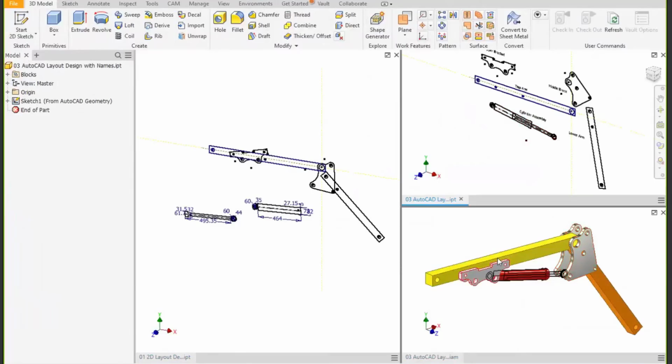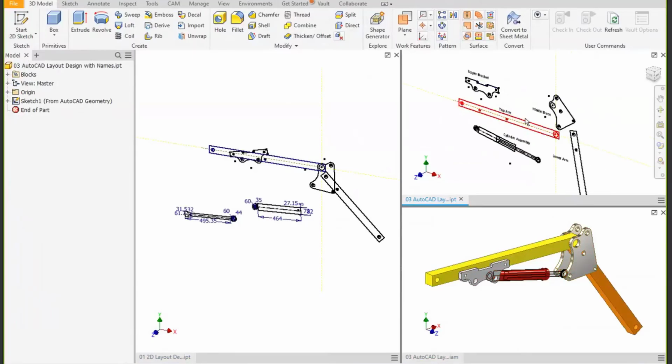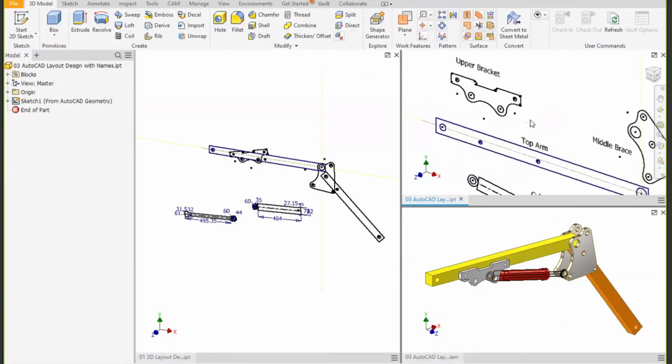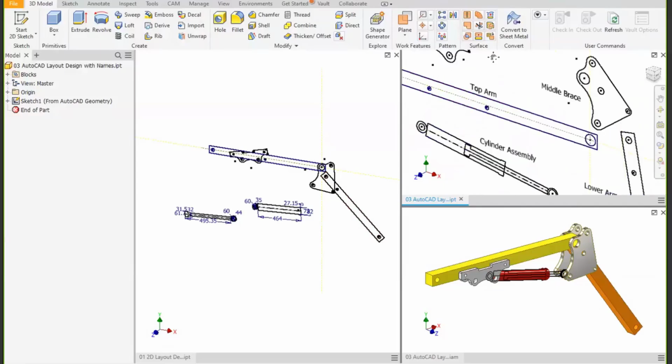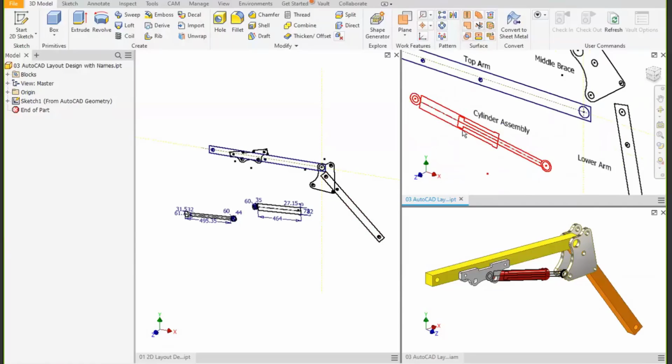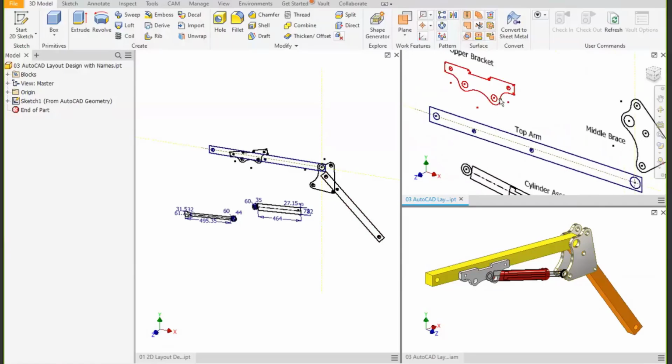So essentially, this is going to be our end result, starting with this. This is a form of skeletal modeling. We're dealing with wireframe geometry that allows us to create an assembly at the sketch level, and even a subassembly. We'll get into how we can build a subassembly at the sketch level. The geometry in this case came from an AutoCAD drawing, so I carefully picked what geometry makes sense to bring over. I didn't just select the entire drawing.